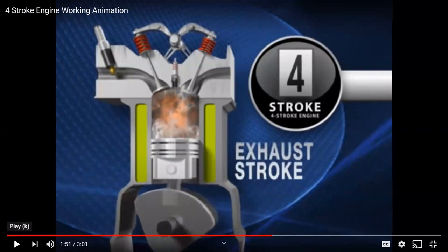Now, at the end of that adiabatic expansion, you're already down to the top of the isochore on the right side. So remember, that short little isochore on the right side includes two strokes, the exhaust stroke and the intake stroke. So here's the next rather confusing point about this. For all the heat engines we've talked about so far, all the PV cycles, we imagine that we're working with a fixed quantity of ideal gas. The number of moles is fixed and the system is closed. There's no way for gas to get in and out. But here, obviously, the air that's just been involved in that power stroke is about to get exhausted through a valve, and it's not coming back.